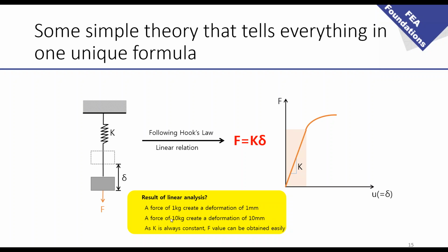And from what you see here, you can think, oh, what if I increase the force to 100 kilograms? Will I have 100 millimeters of displacement? This is where you have to be careful, because if you have that, you're not verifying the assumption that you are in small displacement. And that's where it's wrong. So in this case, you cannot use this formula.